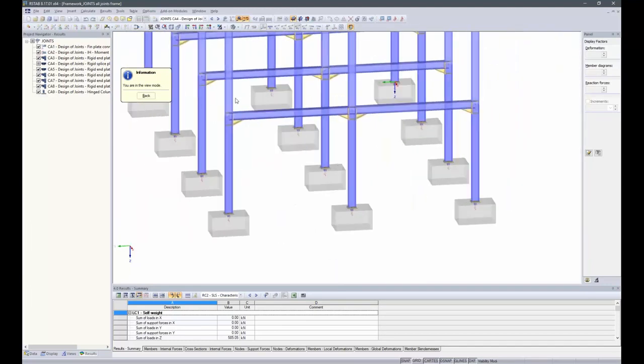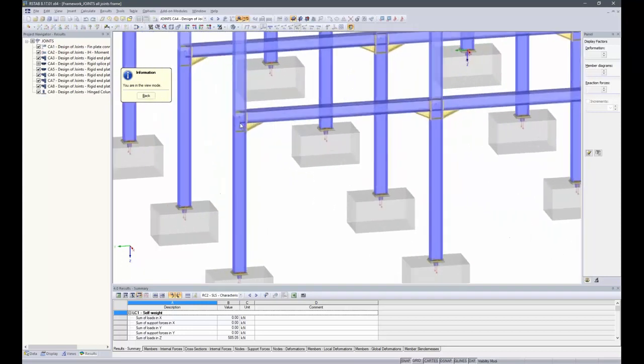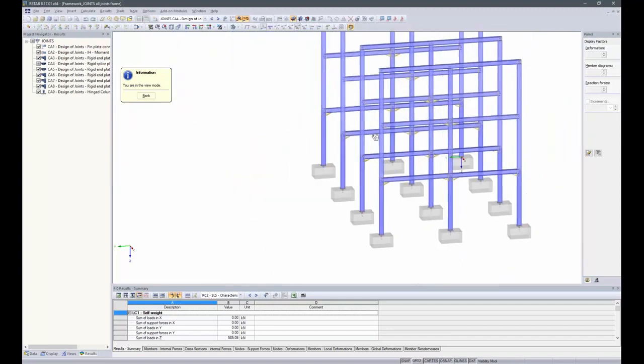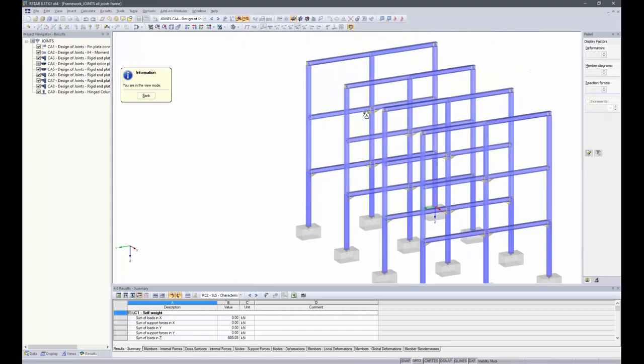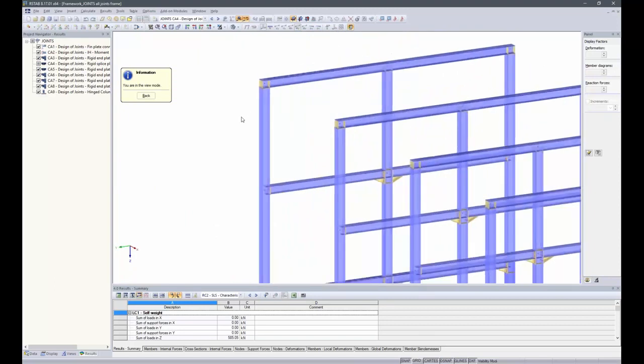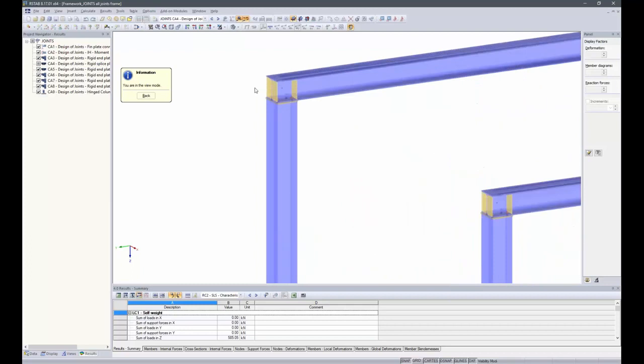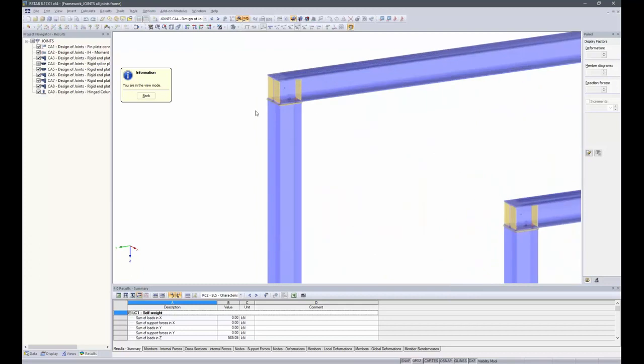Then we have the beam-column-to-beam connections, also for the middle nodes, and one or two connections on the top level, which allow the upper beam to run over the middle column by just inverting the connection. So in this case, the beam and the column would be inverted in the module.